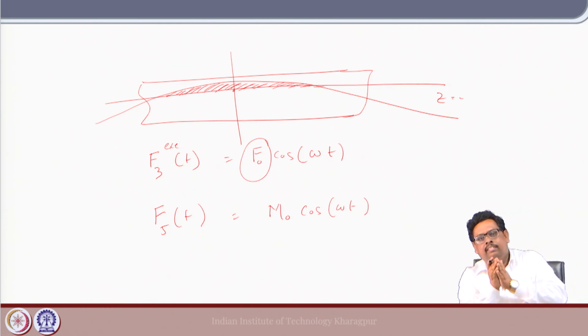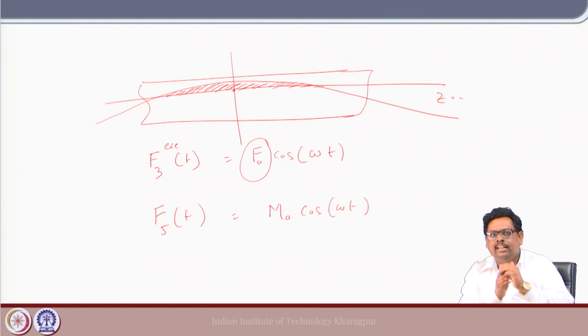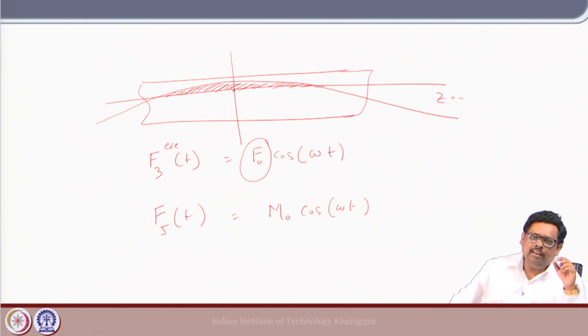For the low frequency limit this really works, because at that time there is no phase between the wave and the response. Therefore, you can take the phase as 0, and in a very simplistic way you can calculate the exciting force with this expression, and then you can write a strip theory code.